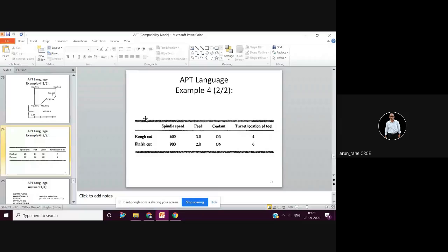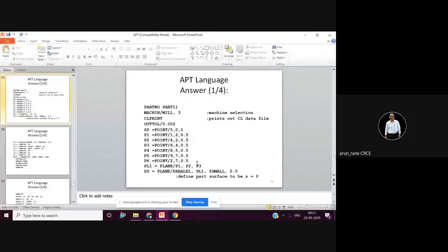Generally, for cutting we don't use the RPM, we use the cutting speed. So for MS and HSS tool, it is 25, and for MS and carbide, it is 100 meters per minute. Remember the unit, meters per minute. And since it is meters per minute, in the formula V is equal to pi dn upon 1000, we divide by 1000, just to make the dimensions on the left hand side and right hand side the same.